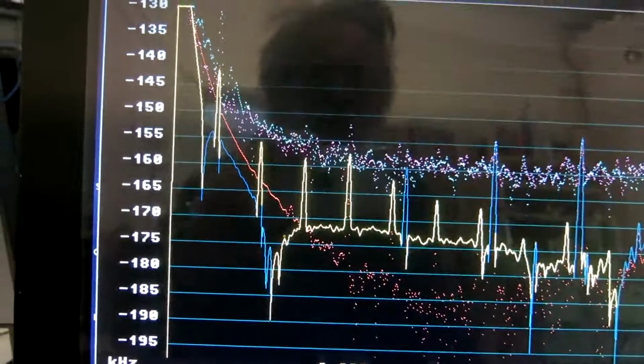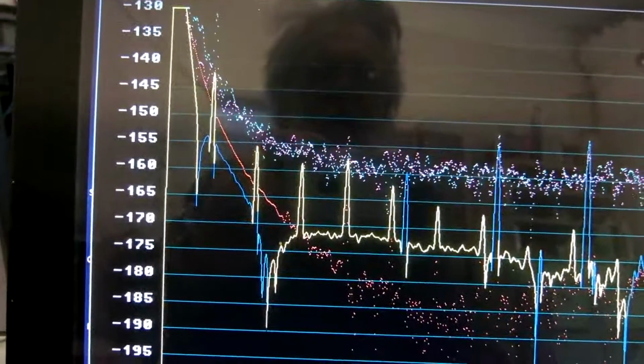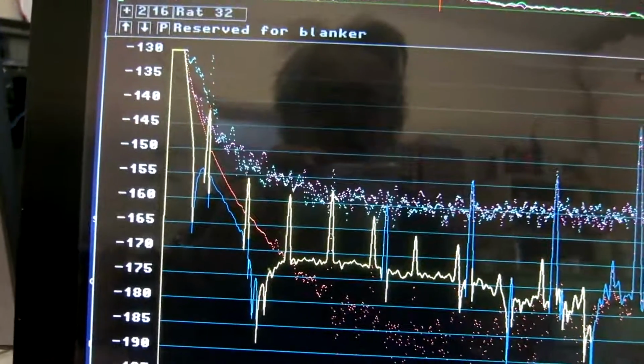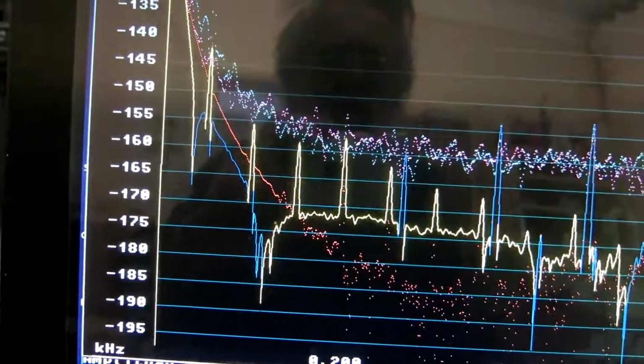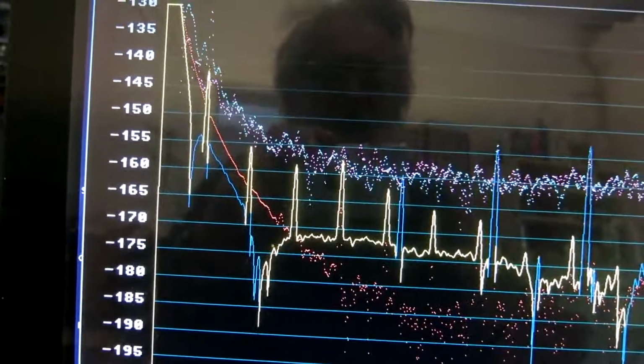This is with a time constant, the smallest one that I have. And I said before they are a factor of 3 for each step on my switch. Actually, I have resistors 1, 3.3, 10, 33, 100 and 330. So now I am at the value 1 and the biggest is 300 times bigger.